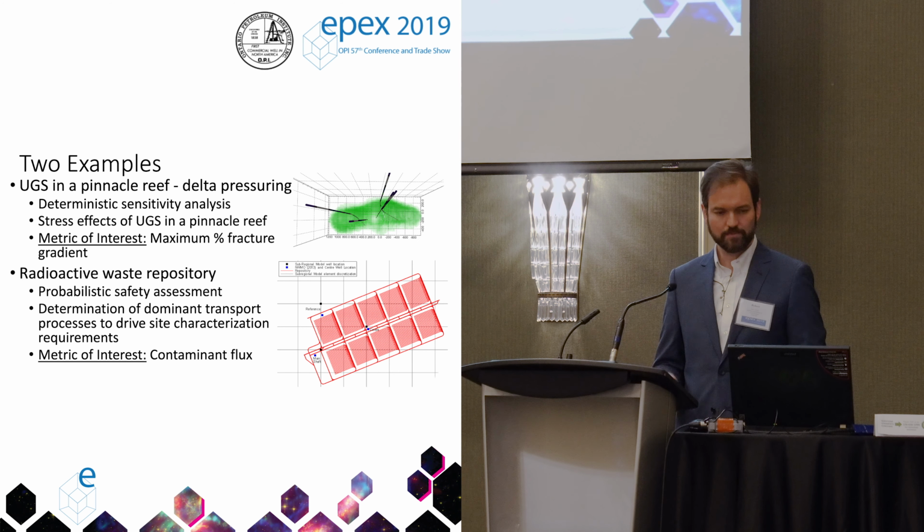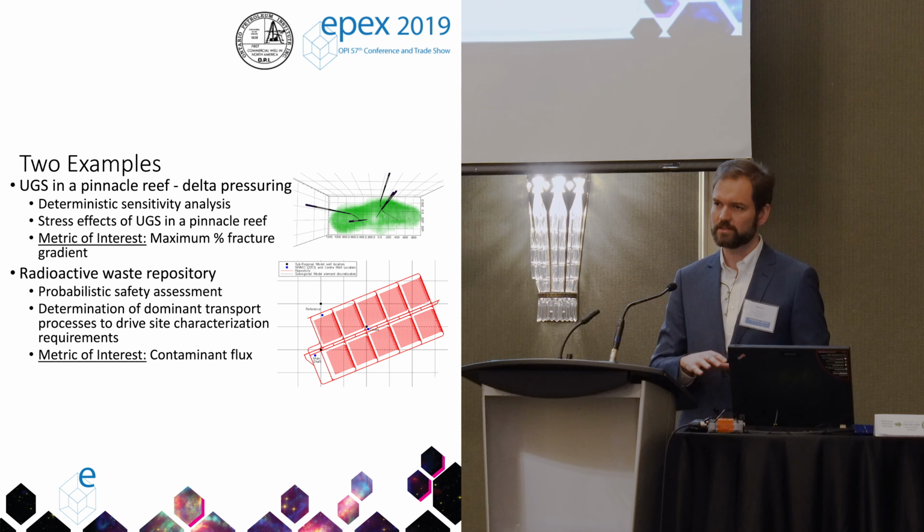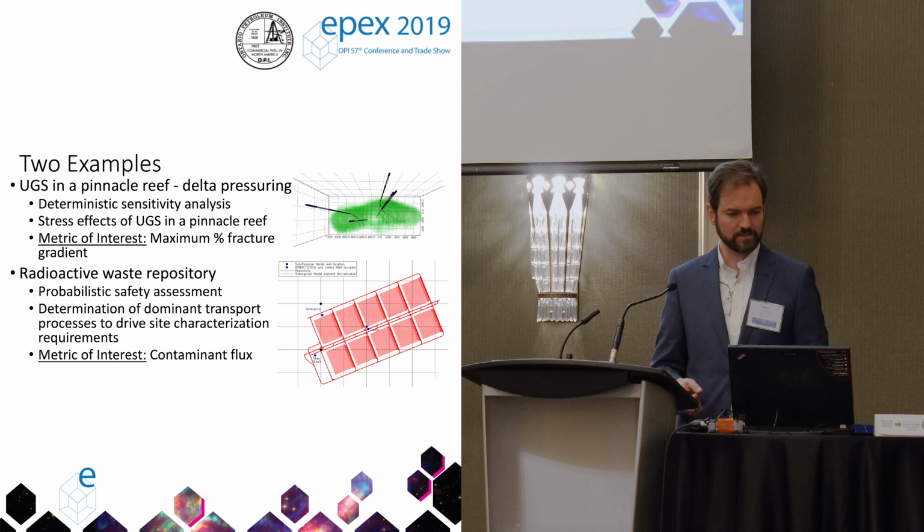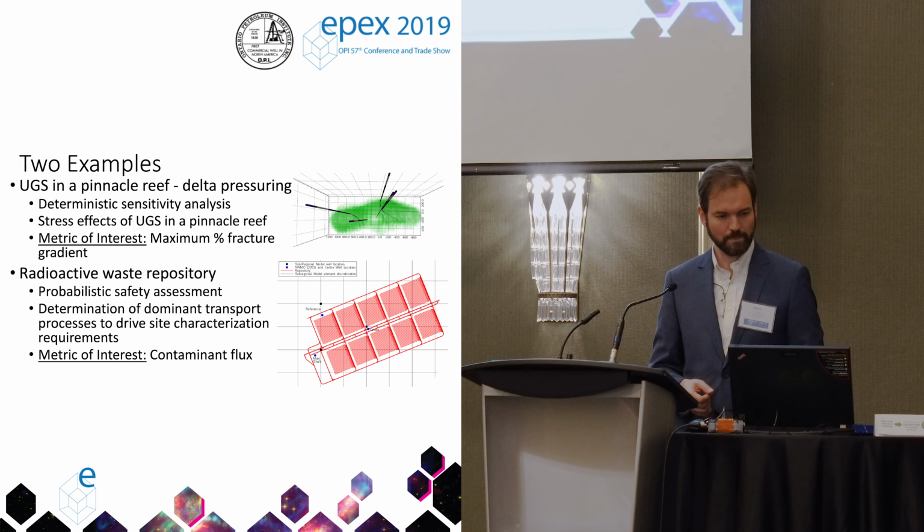So I'm going to look at two examples. One is underground gas storage in a pinnacle reef, which, as you all know, there's lots of in Southern Ontario. This was a project where we did more like a deterministic sensitivity analysis. It wasn't probabilistic in the sense that I was talking about previously. Our metric of interest here is the maximum percent fracture gradient.